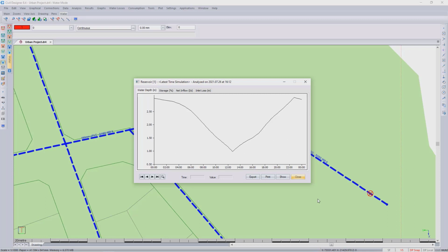This could be a problem if we're now going to bring in hydrants. We might need to switch it on earlier. So just take into mind that you need to actually cater for your reservoir when you've added your fire hydrants.